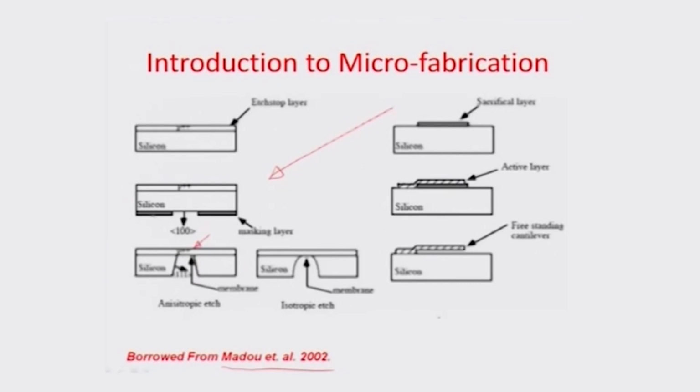So, you can formulate a small cavity here using resist, and so this can be used as an etch window, and there can be an etchant which is selective to P double plus, which is highly doped positive silicon on the other side, and so the material starts etching away in an anisotropic manner, thus formulating a 54-degree angle, and based on this it just goes up to the selective layer here, which is the P double plus layer, and stops the etching process, thus creating a membrane.